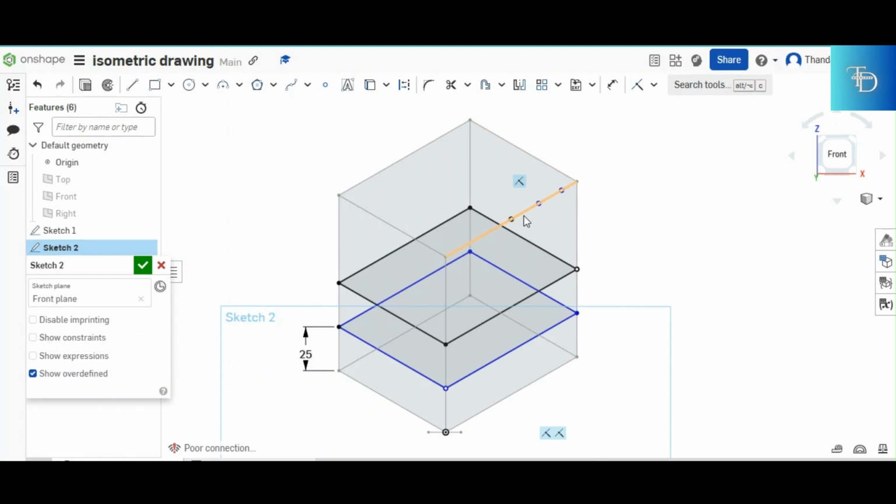We marked at what? At this angled line here. So every line that is parallel to this line right here where you make the dimension should be marked with the same dimensions, which means the 10 millimeter should rotate, and then it goes back where it started. Every single dimension that you insert there, it rotates.